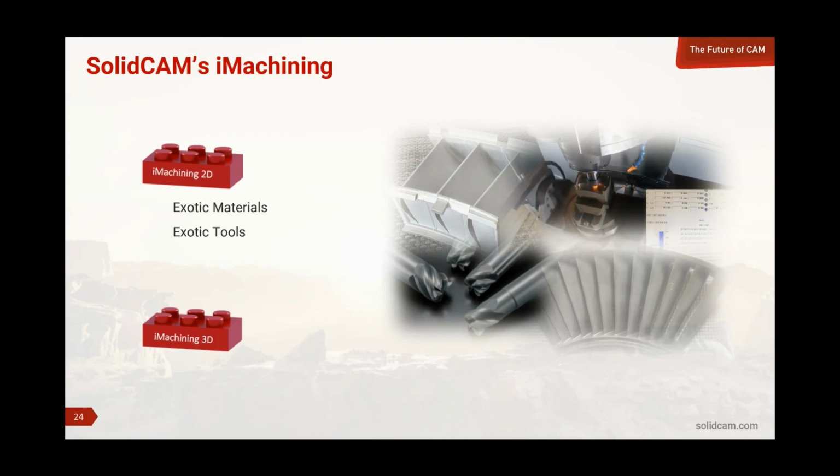Now, in this video, we're actually cutting almost 10 times deeper than anybody's ever cut with carbide tooling, at about 2.5 to 3 times faster than they do with carbide tooling or any other program. And we're getting about 3 to 4 times the tool life of what they would get in the other performance ranges with a carbide tool. So this gives us a really interesting ability.